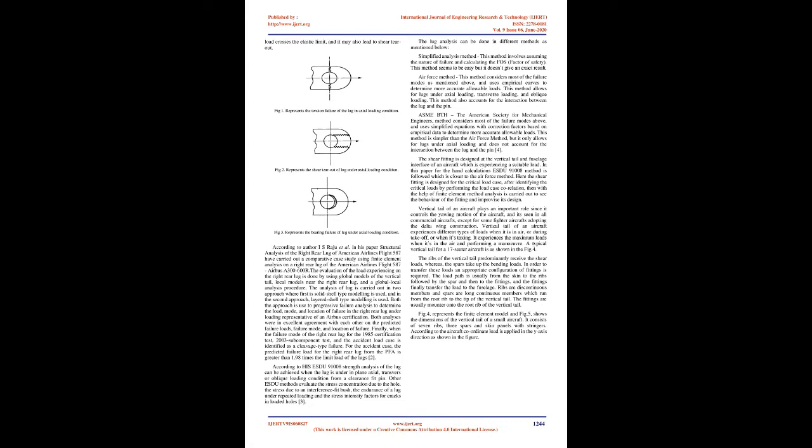A shear fitting consists of two main parts, namely the lug and a flange. A lug, also known as a lifting lug or a pad eye, is essentially a plate with a hole in it where the hole is sized to fit a clevis pin. Lugs are used in combination with clevis pins to transmit load between different mechanical components. When axial load is applied on the shear fitting, the lug can fail under different conditions as mentioned below. 1. Tension failure.